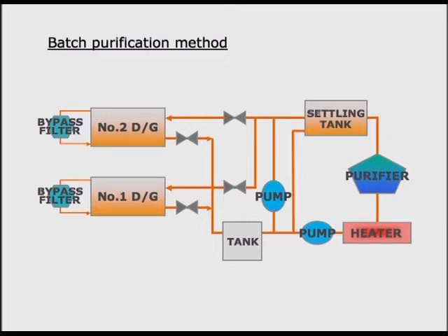For batch cleaning treatment, the lube oil is regularly replaced by the cleaned lube oil. Therefore, you need to determine the replacement interval by watching the dirt level of the lube oil in the sump tank.